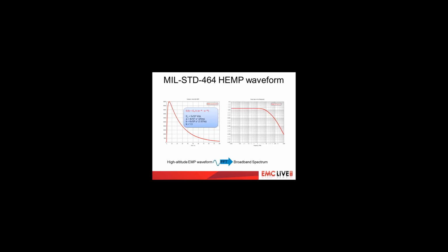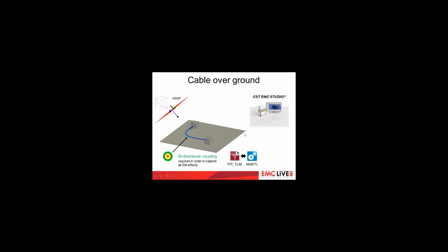Templates are available in CST's Studio Suite to help the user get a good starting point for different kinds of simulations. The EMP template creates a model with a free space environment and a plane wave source, and the direction of the wave is easily configurable. The EMP double exponential waveform is conveniently predefined and applied to the plane wave.